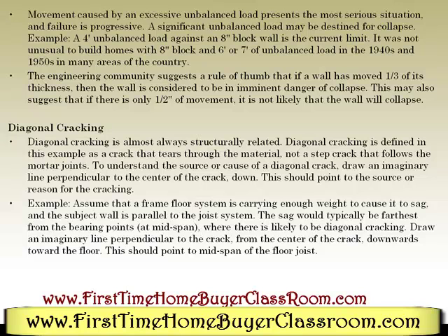Diagonal cracking is defined in this example as a crack that tears through the material, not a stepped crack that follows the mortar joints. To understand the source or cause of a diagonal crack, draw an imaginary line perpendicular to the center of the crack, downward. This should point to the source of the reason for the cracking.